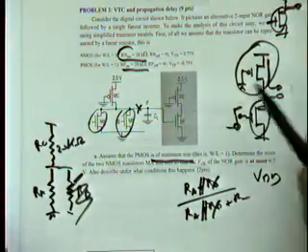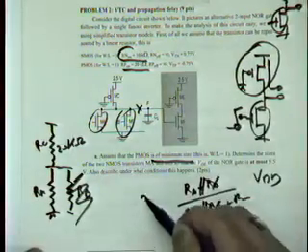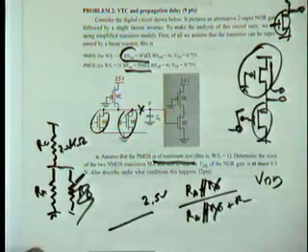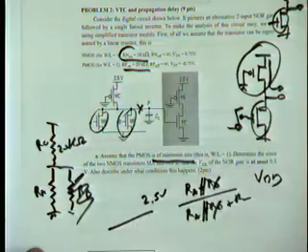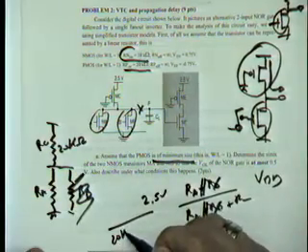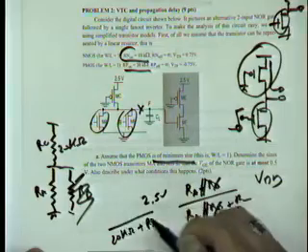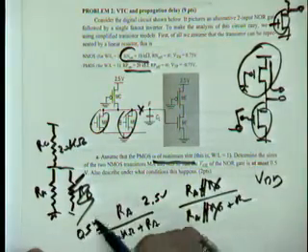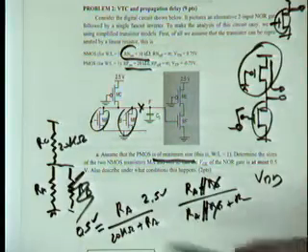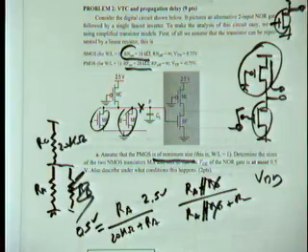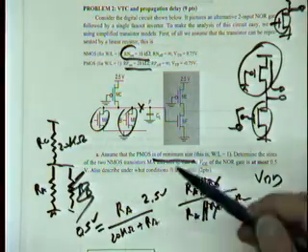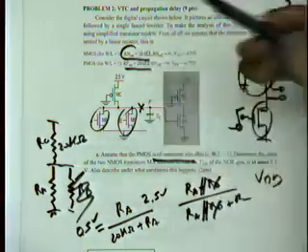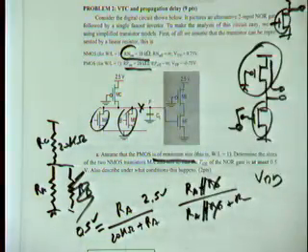Now life is easy because I know the supply voltage is 2.5 volts. We know that RC is going to be equal to 20 kilo ohm. So you have 20 kilo ohm plus RA times RA, and you set it equal to 0.5 volts. Out of that, I can solve RA right away. I can tell you what the value of RA should be to get 0.5 volts max. And then you can divide them, and you figure out the size of the NMOS transistors.